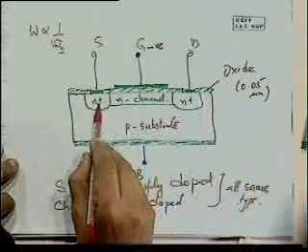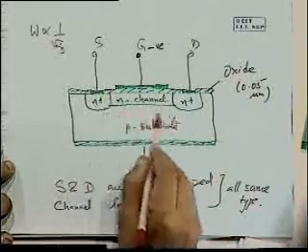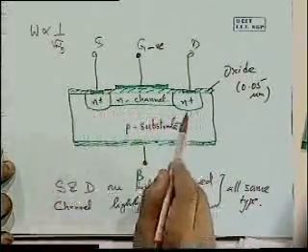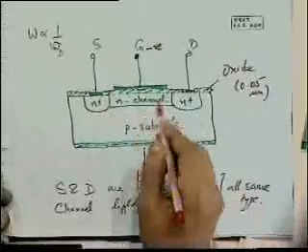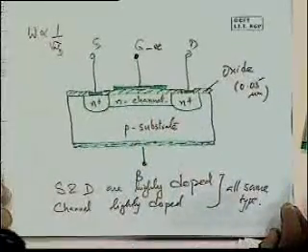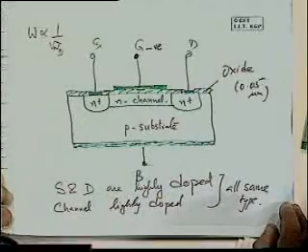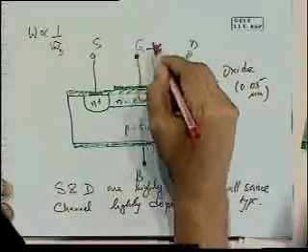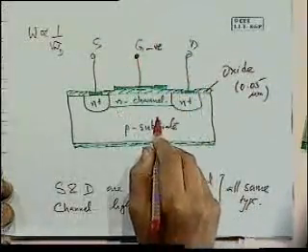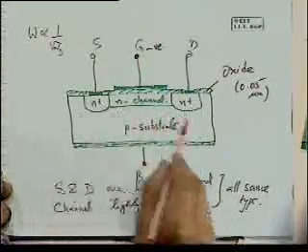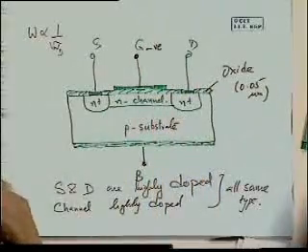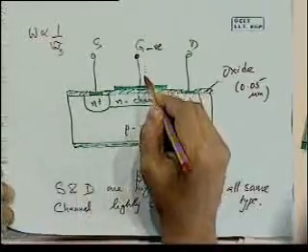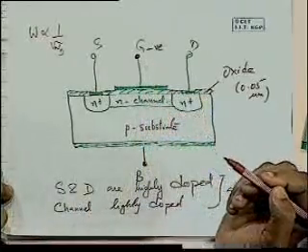What that means is that the N channel is less conducting between source and drain, because the channel is partially depleted. So by biasing the gate negatively, we get a partially depleted channel, lower current chances to go between source and drain.